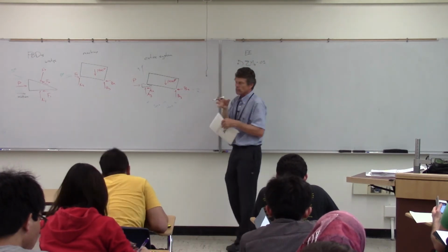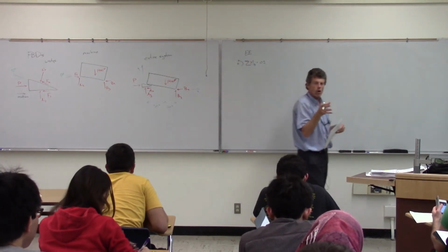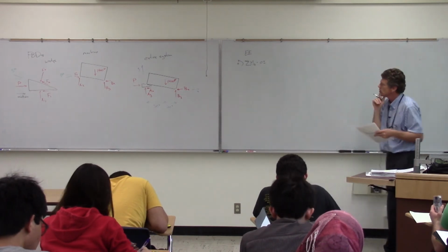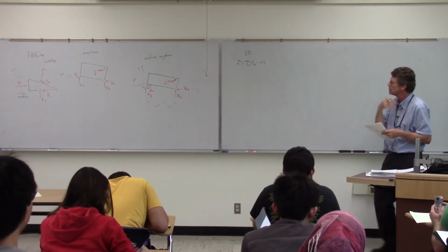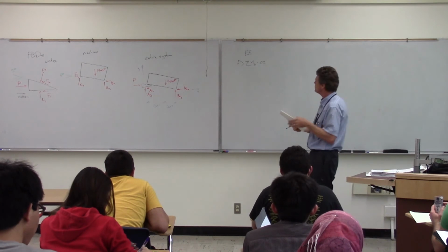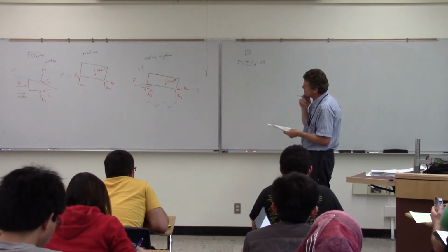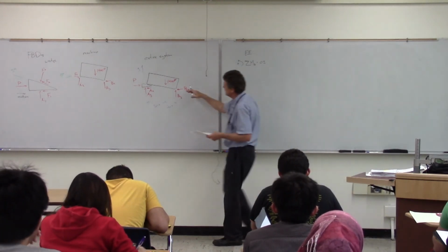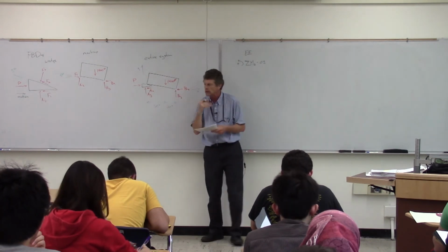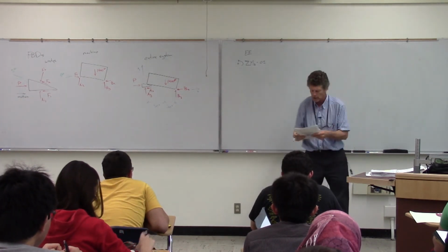And a lot of these friction problems you'll see are basically solving a two-dimensional equilibrium problem to start off with, to start developing these normal forces and that sort of thing. So we can take this one and note that I can take a moment at B, noting that Ax acts through B there, so it won't participate in that moment equation.